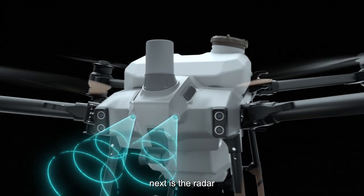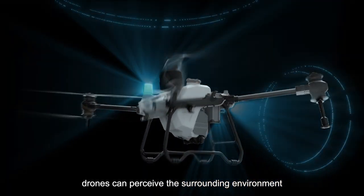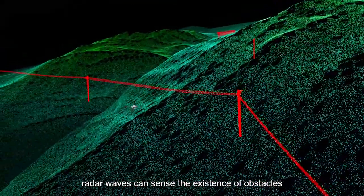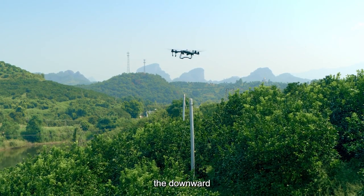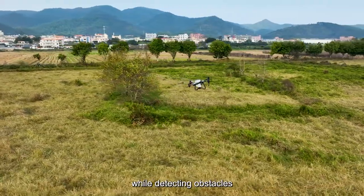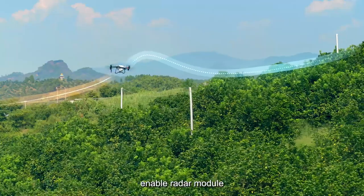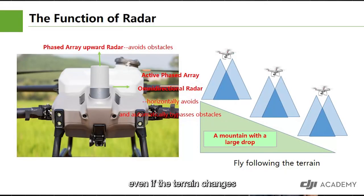Next is the radar. With radar waves, drones can perceive the surrounding environment in real time. Radar waves can sense the existence of obstacles, so as to realize the function of obstacle avoidance. The downward radar wave can determine the height of the drone while detecting obstacles, supporting holding the height while avoiding obstacles. Enable the radar module, and the drone will follow the terrain while flying. Even if the terrain changes, it can keep the relative height to the terrain unchanged.